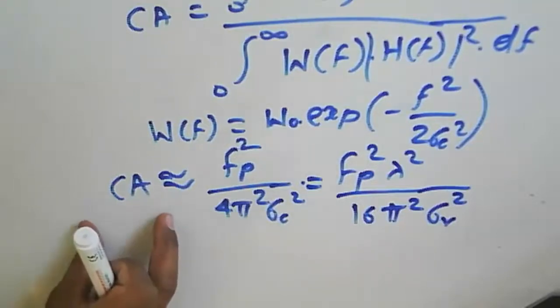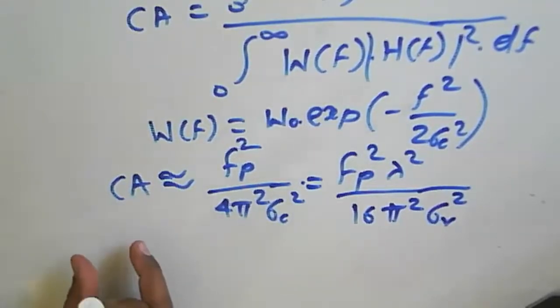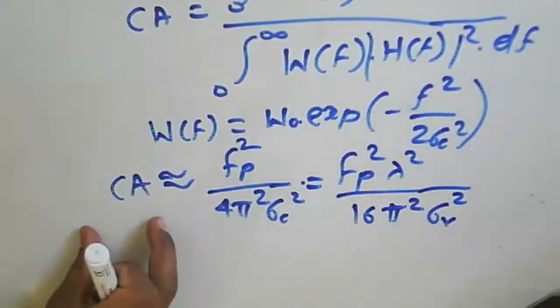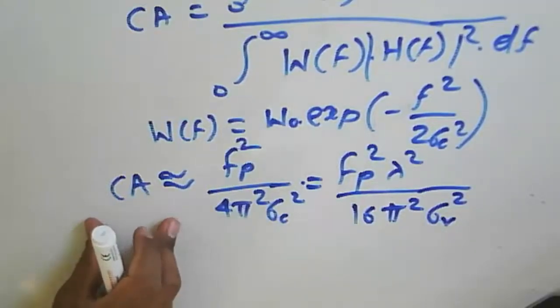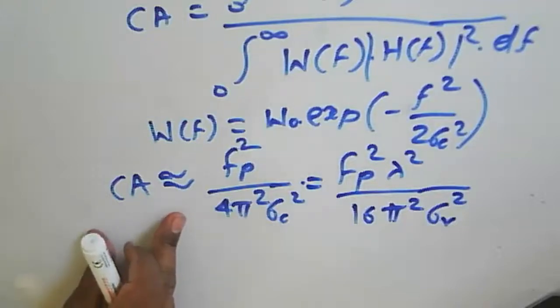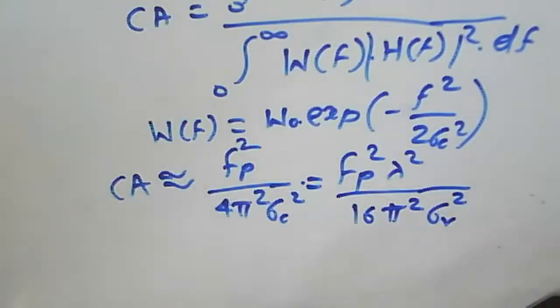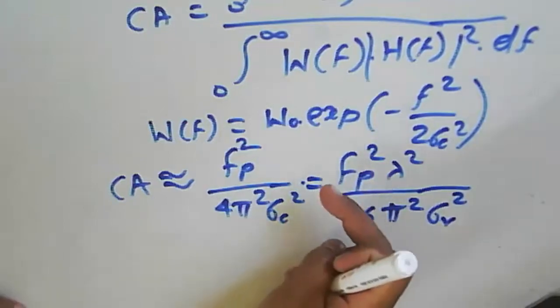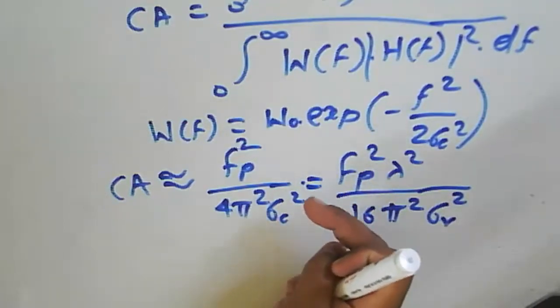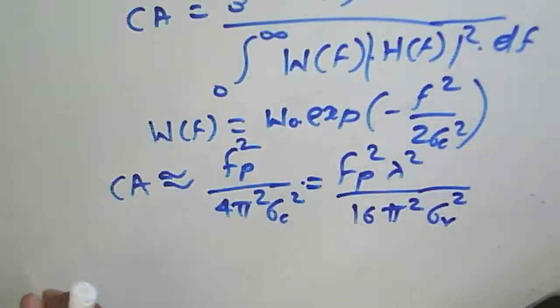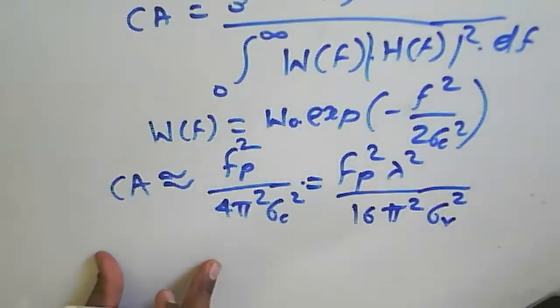But the clutter attenuation by the single delay line canceller is not sufficient, as we said earlier. There will be blind spots. Some targets have the same repetition frequencies, so that will not be avoided. So we can say there are limitations of a single delay line canceller, because some clutter is not removed there.